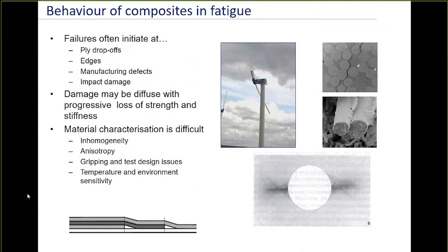Another feature of composite fatigue failures in practice is that they're often associated with features or defects that have been introduced during the manufacturing process. These could be things like ply drop-offs, where you introduce a resin-rich region.